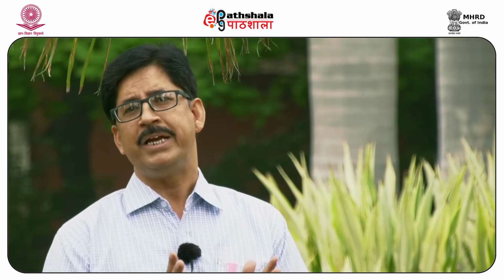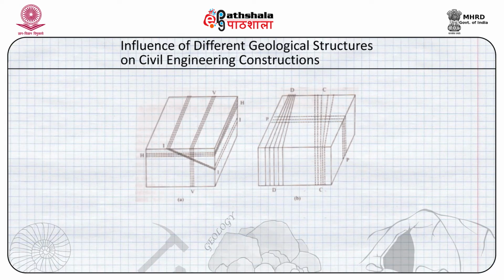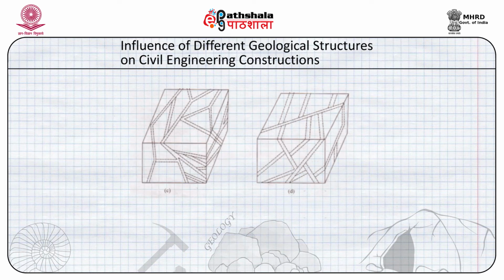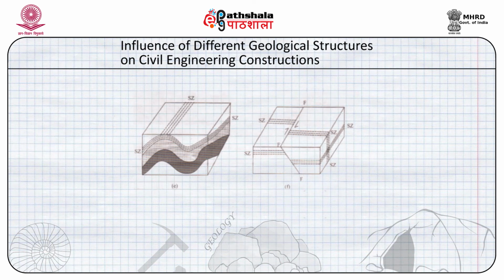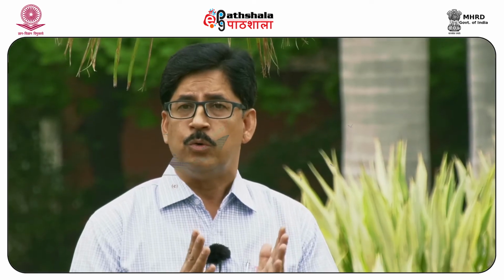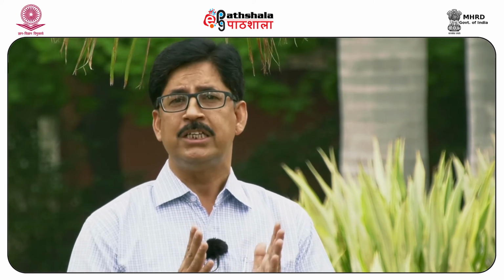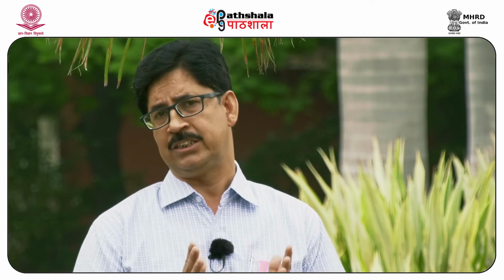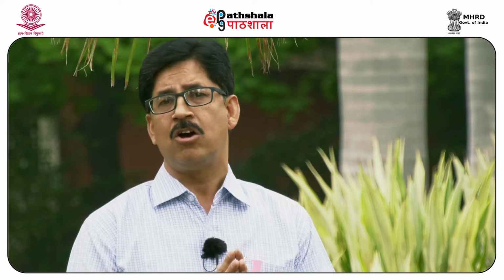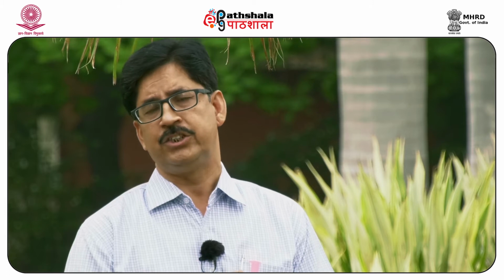The shear zones may come in different fashion, they may be of different types, different thickness, different lengths, but most importantly, along the shear zones rocks may be pulverized. The rocks may be pulverized to very fine grained material termed as gouge. The rock may be pulverized to somewhat coarse grained material, that is sand sized material, called mylonite, and the rocks can also be pulverized to a gravel sized material which we call breccia.